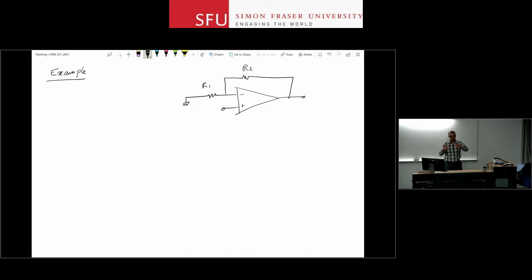So let's say the equivalent resistance down here is 10 kilo ohms and the input resistance of your probe is 10 mega ohms. Well, if you put a 10 mega ohm resistor in parallel with the 10 kilo ohm resistor here, nothing is really changing by much. The error that you produce by touching that node with the probe is negligible. But if you have a high impedance node, so the equivalent impedance here is, let's say, 1 mega ohm, and you touch that node with a 1 mega ohm probe, then the voltage at that node will immediately drop by a factor of 2. So whatever you read on the voltmeter is not really the actual voltage here when you remove the probe. It's going to be half that, right? Or a fraction of whatever it should have been.